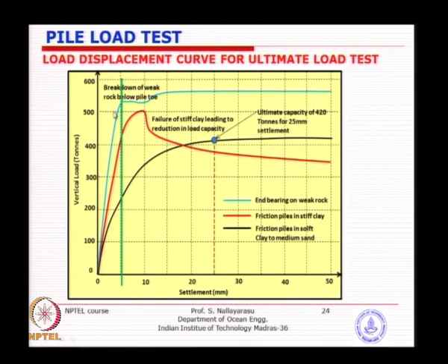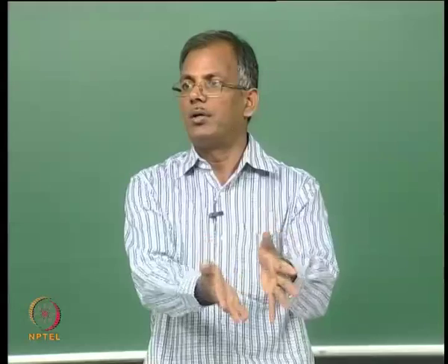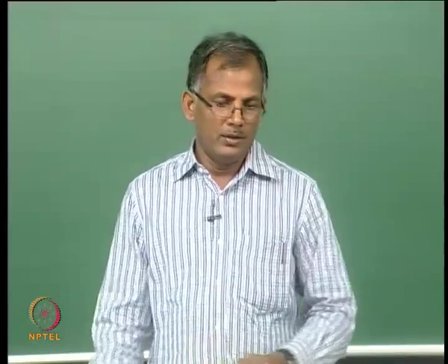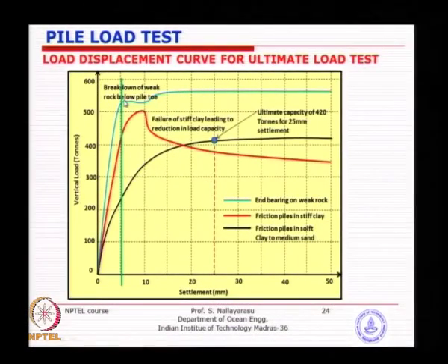And if you take this one, you won't get anything better, isn't it, because you are having almost a linear relationship. If you take that, the capacity of say 550 tons divided by straightaway factor of safety of 3, you will get somewhere around 180 tons. Whether it is 10 mm or 5 mm, you are going to just linearly prorate, so it does not matter. So that is the idea of constructing or establishing load displacement characteristics up to failure.